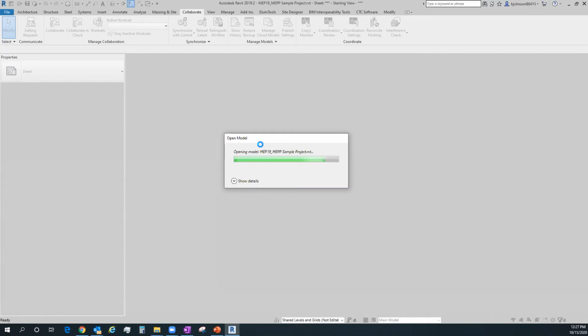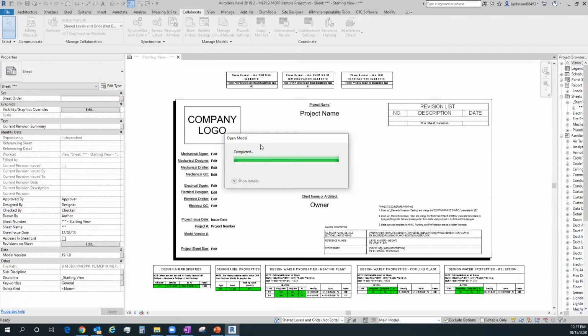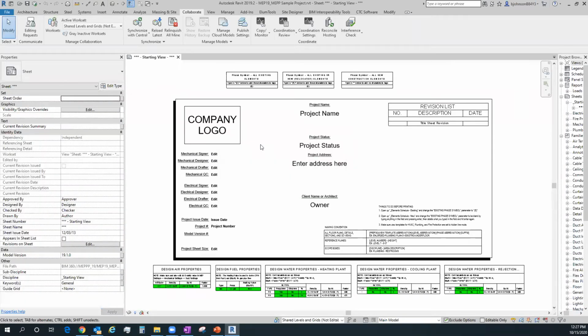Anything under 500, unless it's a warning that I'm not fully aware of whether or not it's going to do something bad in my model, the majority of the time I kind of ignore it until I have a real problem like a crash. And then I really want to know what those warnings say, right? If it's over 1,000, then I usually urge the team to make sure they start doing warning cleanup.